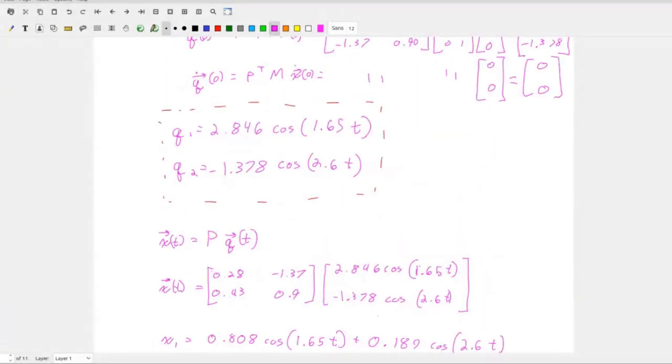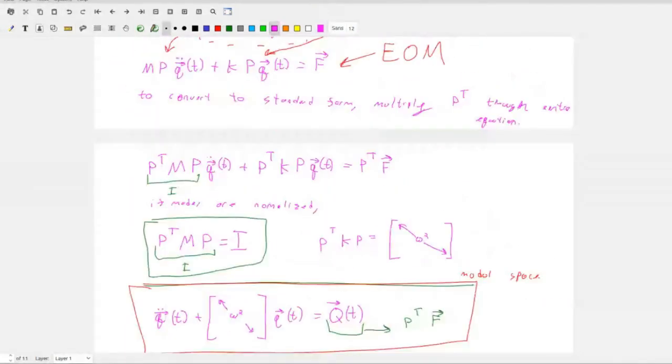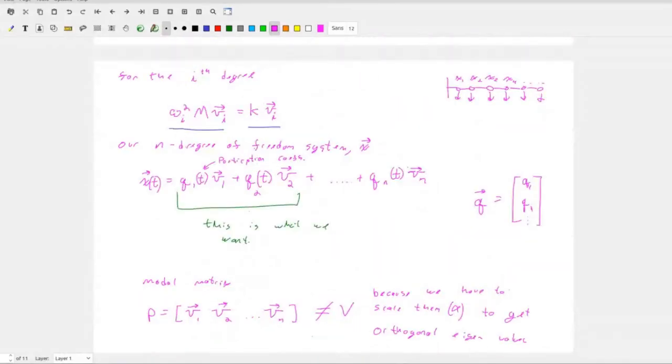We have two participation factors, Q1 and Q2. Let's just take Q1. That makes sense? And we can drop Q2. How about that? So if we think back to this equation that we wrote here, we just want what's in green, except here we're just taking the first one, right? But we're taking some amount of our participation coefficients multiplied by our eigenvectors to rebuild our x of t. So let's go ahead and do that.